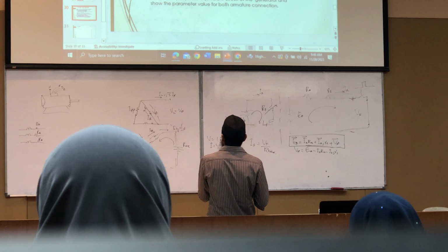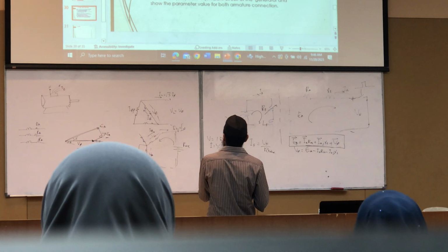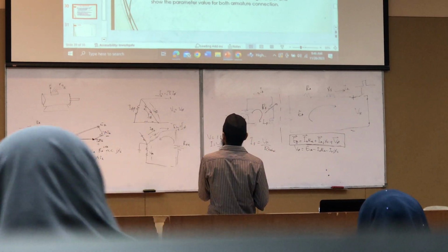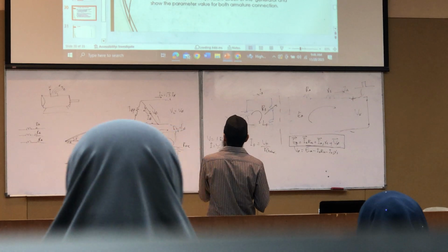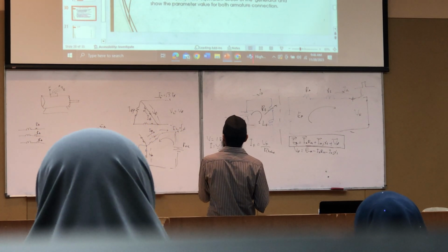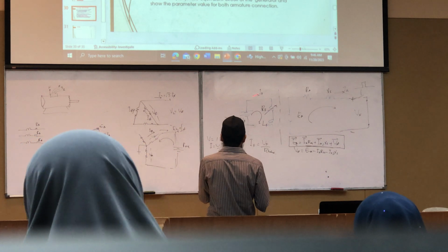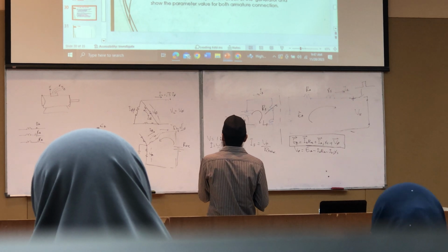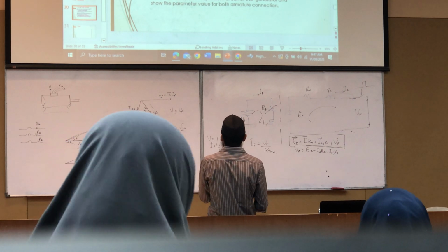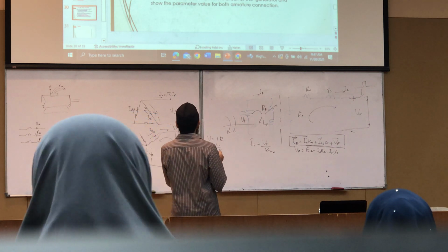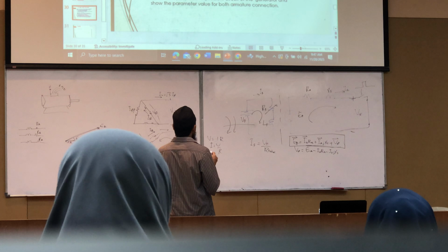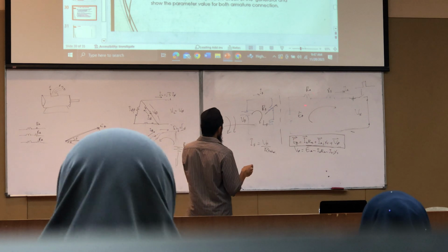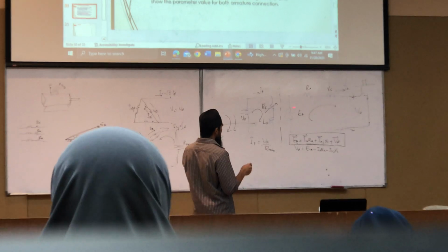The armature short circuit current is 300 ampere. When we perform the first DC test at 10 volt, 25 ampere is measured. So try to find out the single phase equivalent circuit components when we connect the system in Y or when we connect in delta. The final task that we should accomplish is to draw this circuit and indicate what is RA, what is jXS, what is EA.